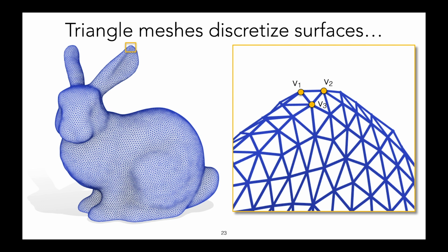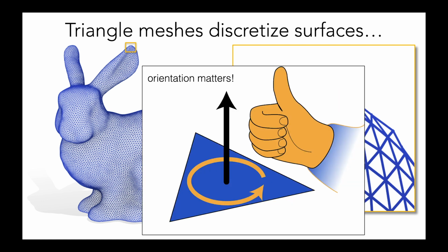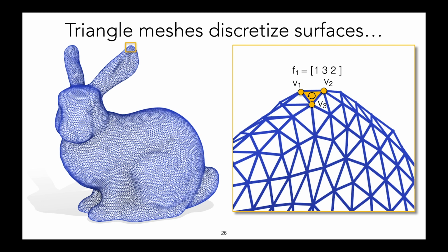Now let's go to the faces. Every face is made of 3 vertices, and we're going to identify it by storing the 3 indices of the vertices. In this case, the orientation matters. We have a convention that, using the right-hand rule, we want this vector to point outside the surface, so that we fix this orientation consistently for all the faces of a mesh. After we have these, we're going to have many faces to store, and for every face, we have a set of indices.